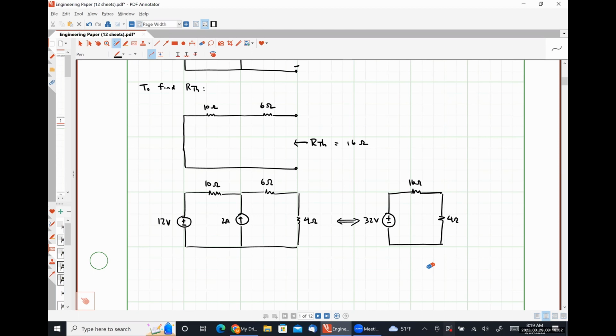And so where that's going to be problematic for us is in determining the Thevenin resistance. Because since we can never turn the dependent source off, we don't have a simple resistor network anymore to analyze and use resistor combination techniques. So we're going to have to get a little bit creative by just using Ohm's law effectively. We'll talk about that more on Monday.